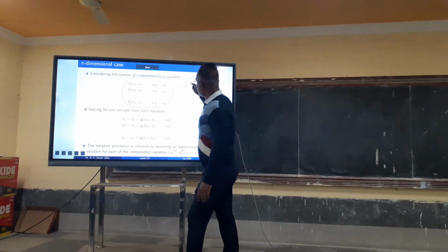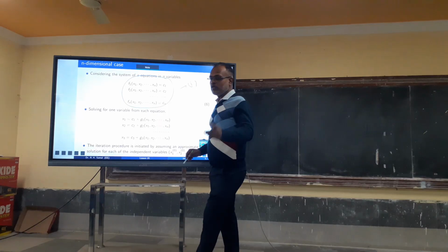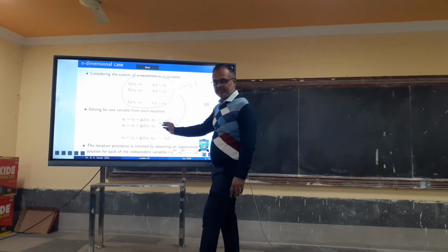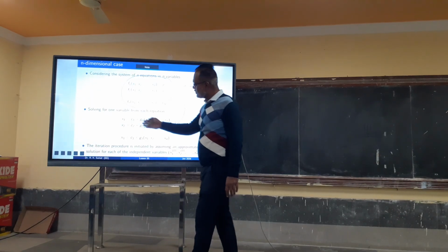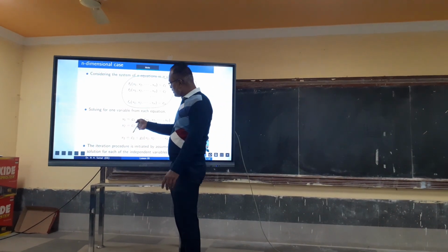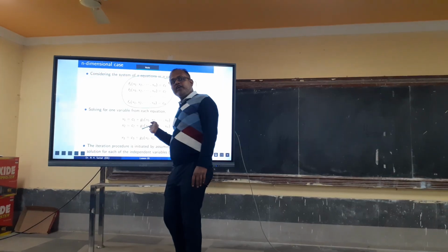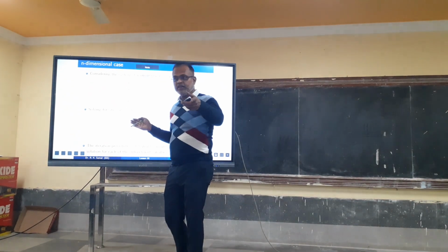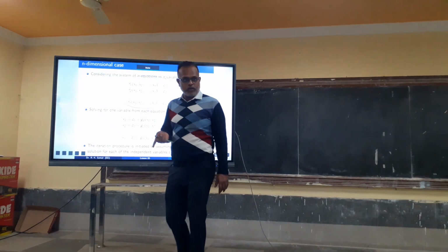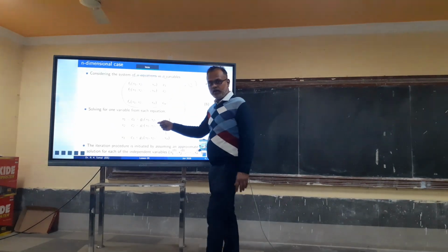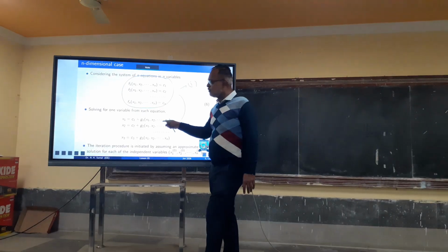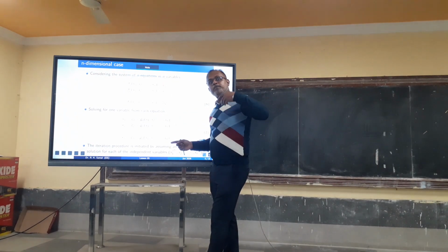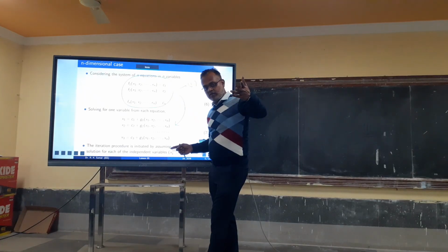This is again step 1, in the first form f(x) equal to 0. Second, we write it in the form x equal to g(x). Consider x1, x2 to be voltages, which are a function of P, Q and Y, and also the bus voltages. V2 is dependent on V1 from the previous iteration.